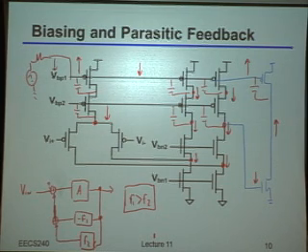So, why is it probably positive feedback? Swing on the cascode PMOS. Uh-huh. Yeah, exactly. So notice the whole trick here is that I had a certain gain to get to this point, right? I then go through yet another gain stage to get to this point, right? And so even if I didn't have isolation from the cascode, I would most likely have more gain to this final output than I did to this point. And so because of that, the gain that would be causing the positive feedback would probably be larger than the gain that would be causing the negative feedback through that path.